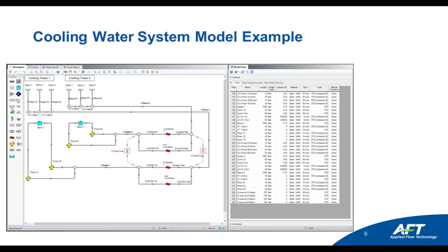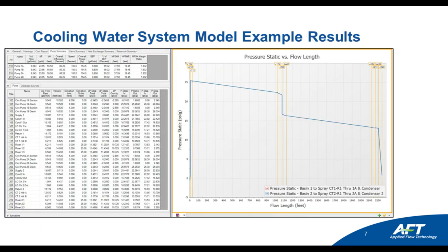That's one way you can still simplify a flow model and maintain a high level of accuracy, by including the effective losses from your fittings with the piping themselves. That way you can reduce the amount of clutter built into the model. Other things you can also include in the piping would be elevation changes. So this is still a relatively simple model, but there's a lot of piping in the system that we're going to be able to capture effectively.